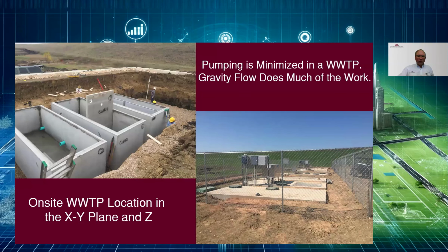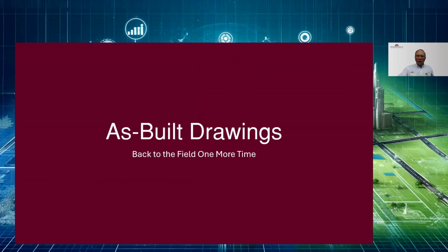Here's another look at tanks we're putting in, part of the wastewater treatment process, going into the ground. The left side is the open tanks being completed, and the right side is finished. These are aerated systems, but what's important is they've got to be precisely installed because of the gravity portion of these systems. As-built drawings.